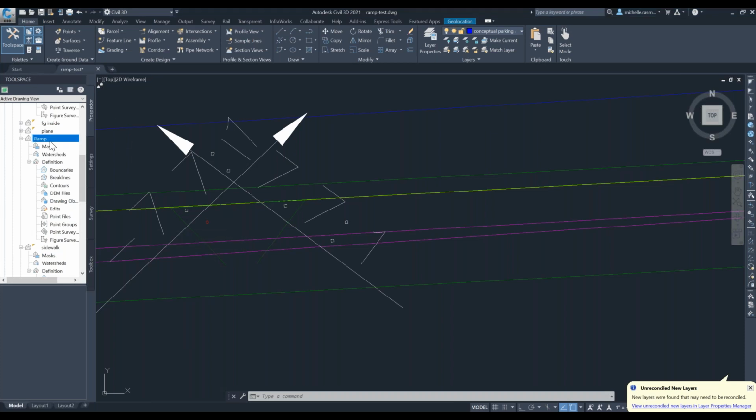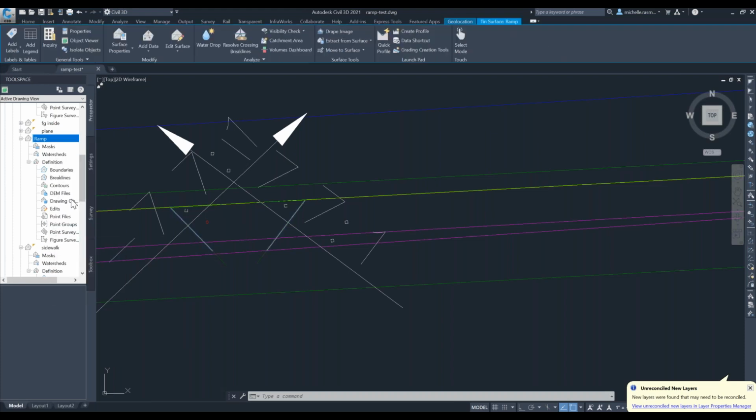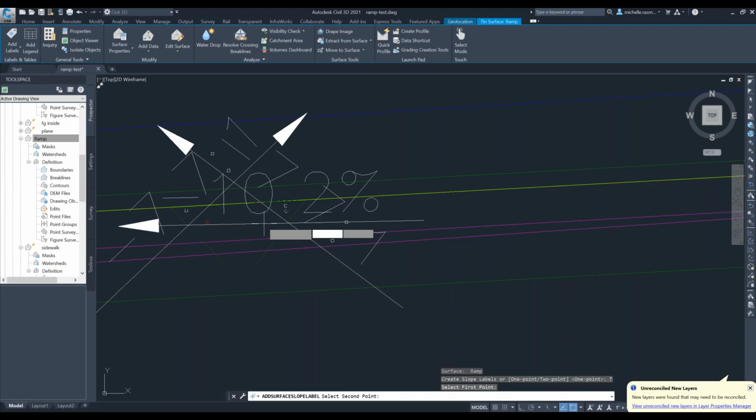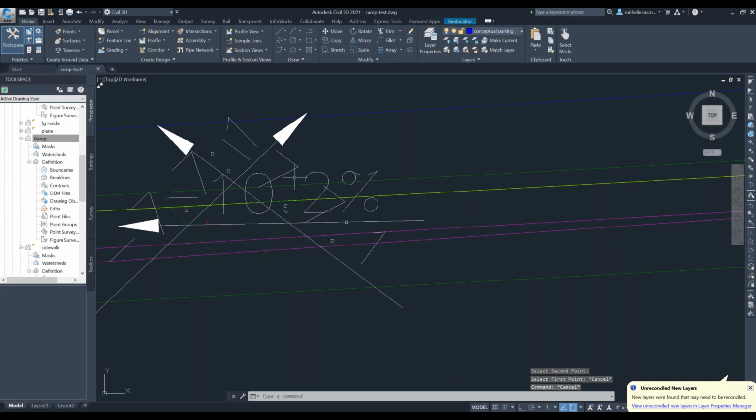And then with a corridor, we have also created sections and left some out, just as I believe Adam has said. We do that same idea, but we will actually add the concrete ramp to the corridor assembly along with the bottom of the curb, which will allow the slope of the curb to match the feature line of the asphalt, we'll say. So we're building corridors off of the feature lines rather than an alignment.